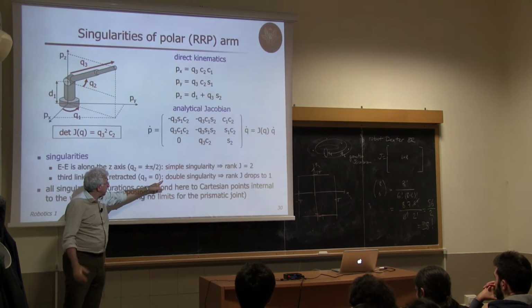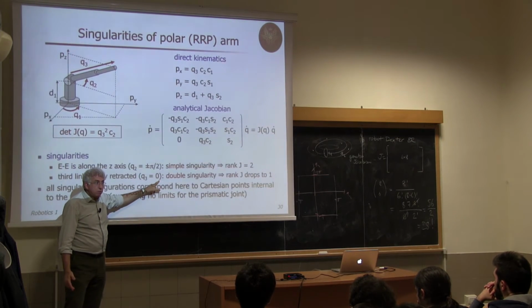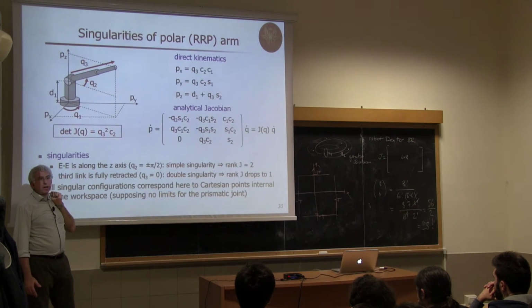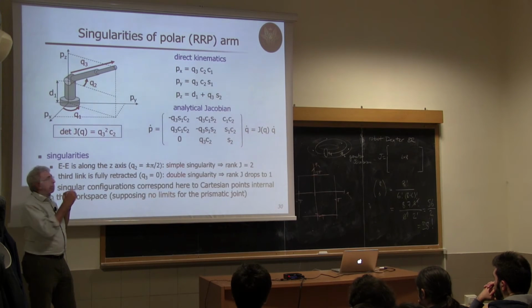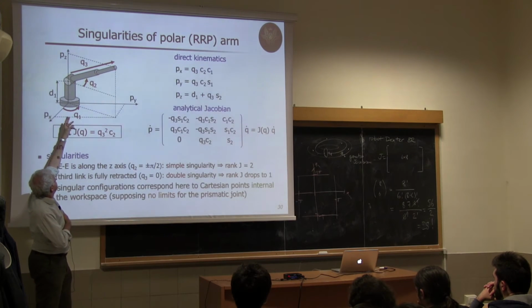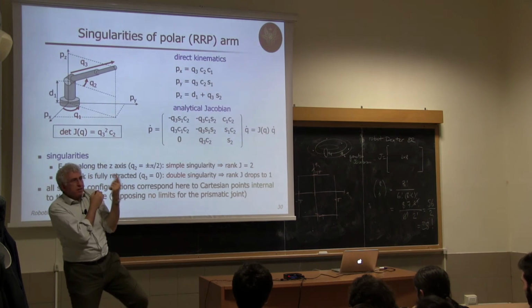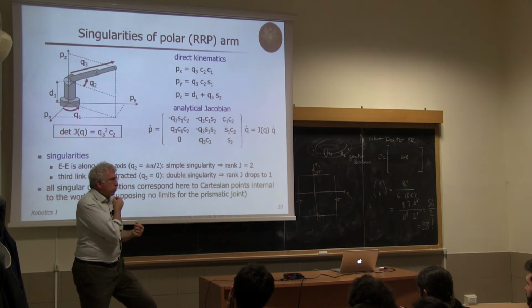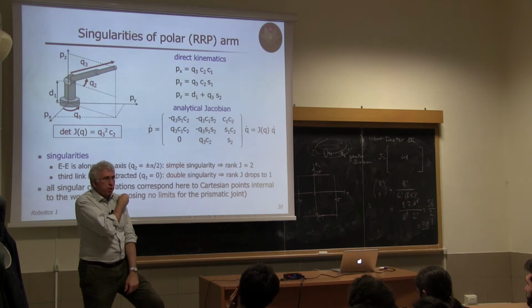Okay? Here, same thing, but even worse. Why? If you remember correctly, Q3 is retracted. So when Q3 is retracted, and I'm assigning a point which is on the shoulder, this is just a single case, but then the position of Q1 is irrelevant, and also the elevation Q2 is irrelevant because I'm not moving this point.